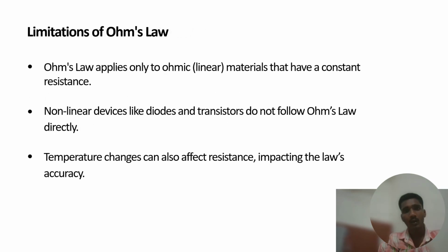Ohm's law applies only to ohmic, linear materials that have a constant resistance. Non-linear devices like diodes and transistors do not follow Ohm's law directly. Temperature changes can also affect resistance, impacting the law's accuracy.